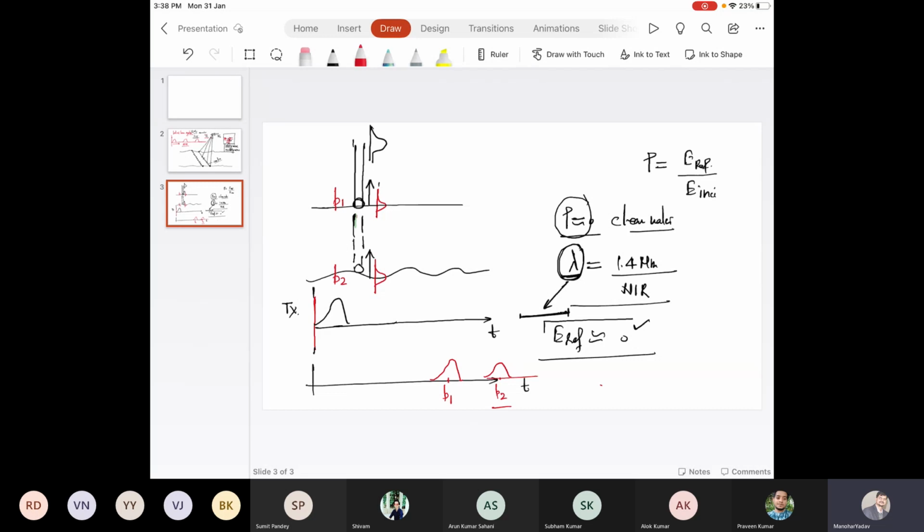Now point P1 and P2, and let's say this is the origin of the laser source. And this origin of the laser source is also considered as the origin of the internal coordinate system of the instrument. Okay. So actually, this is the reference point from where we calculate distance. We'll see how these two returns are further processed, what kind of derived parameters are computed.